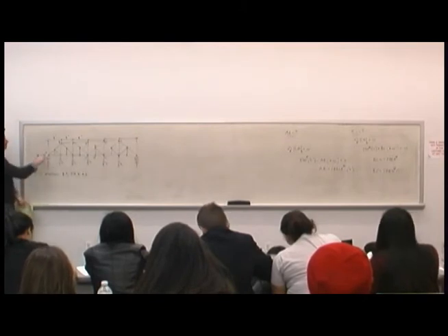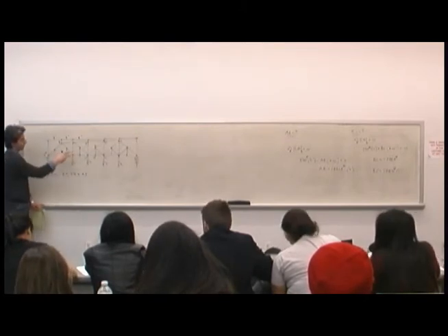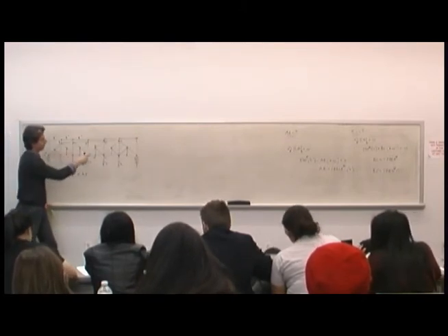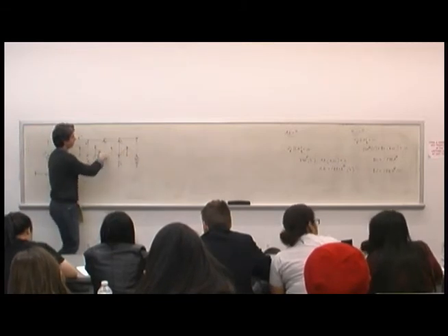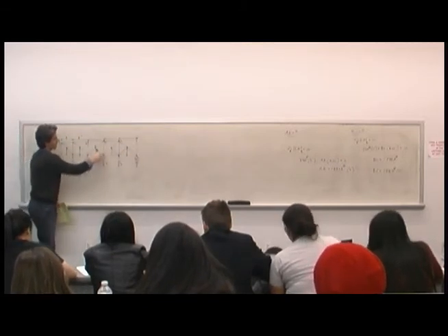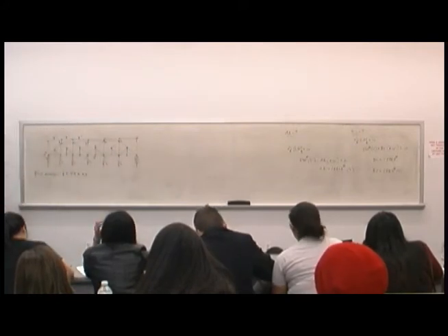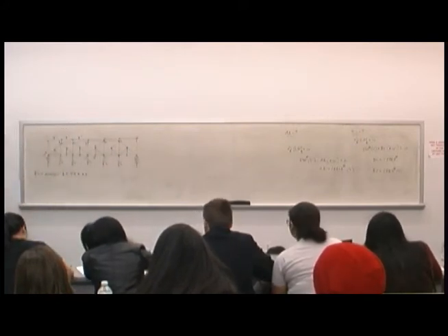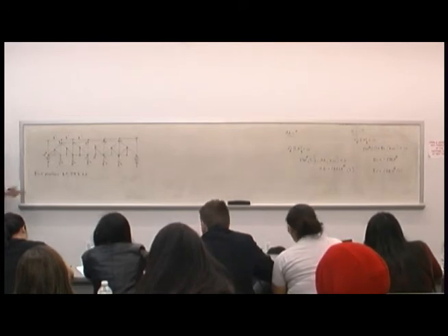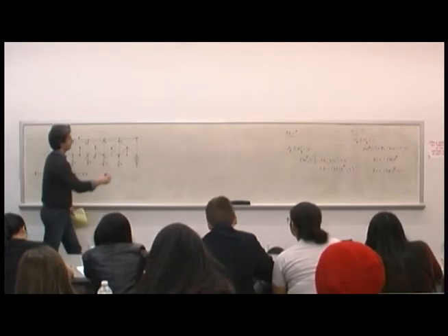If I was to do this by method of joints, it would take me a while to get there, from either side. I could start from here, I could go around, or I could start with this joint, but I've got too many unknowns, so I'm going to need to bring in the reaction somehow. In any event, in order to solve this, I need to find the reactions.